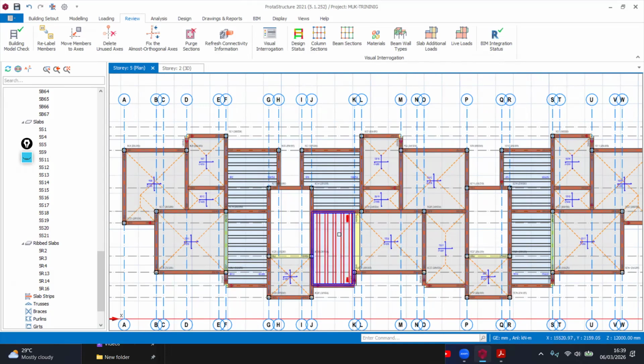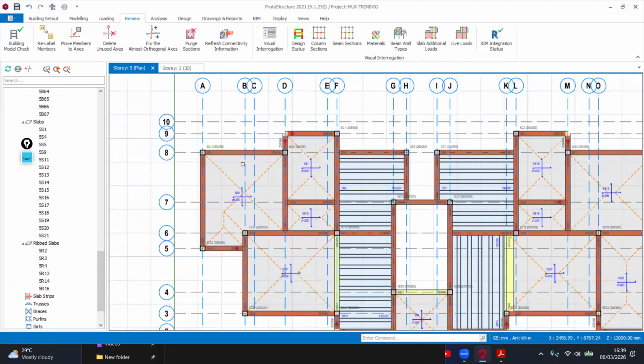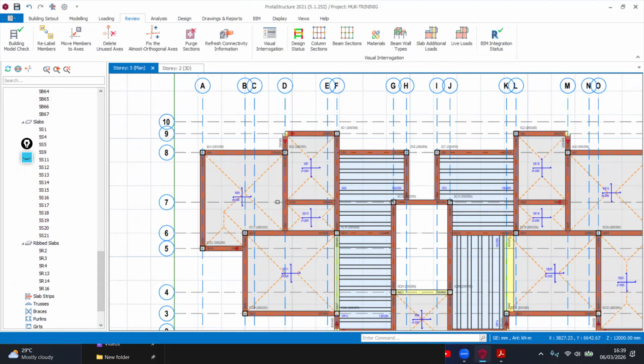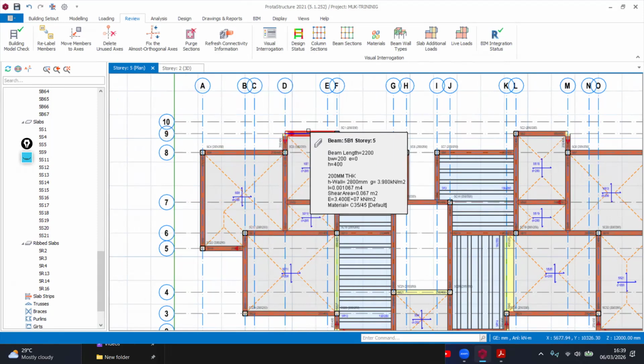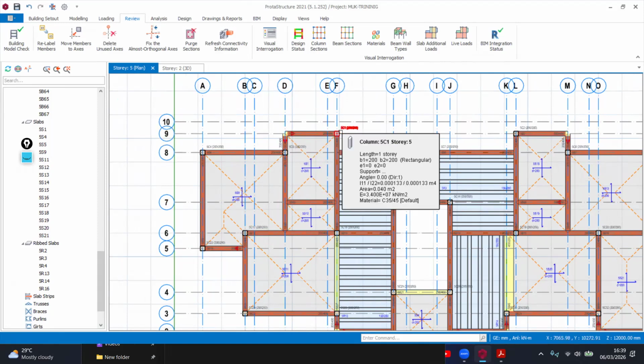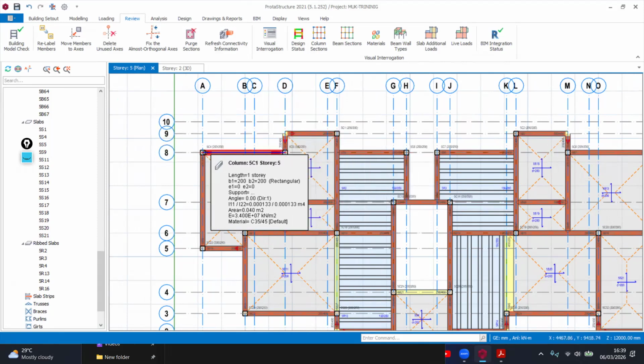Okay, this here where I have the terrace, this is a wall load. We shouldn't have wall loads there. We should instead have parapet loads. Just a parapet wall around these perimeter beams.